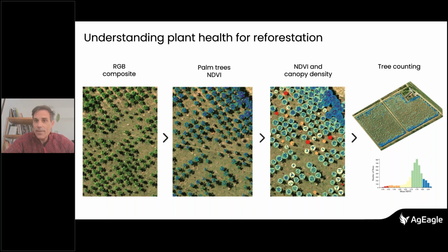Next question about the DLS. Is it possible to work without the DLS? It is. You can work without the DLS, right? The thing is, the DLS is not just a light incident sensor, it's also the GPS of the camera. So it's mandatory to have GPS data for each image that you take. So if you take out the DLS, you need to have another source for the geotagging of the images. So you need a very good integration with your drone, right?